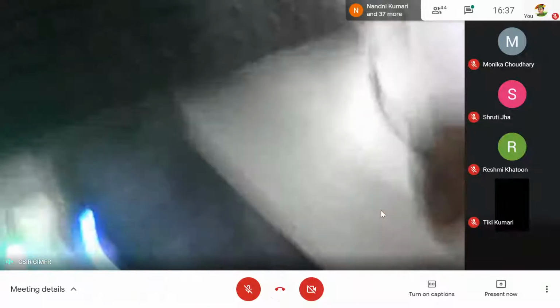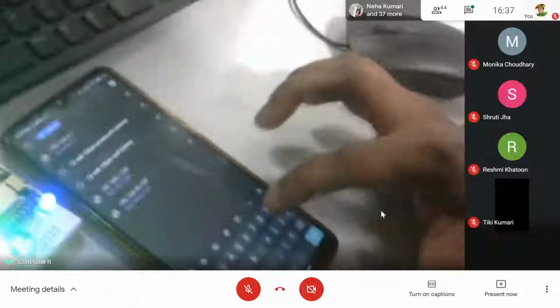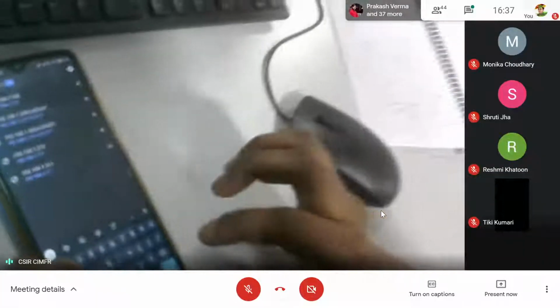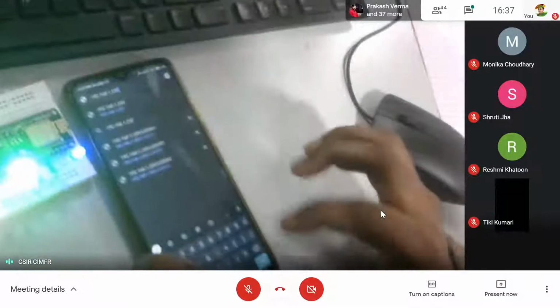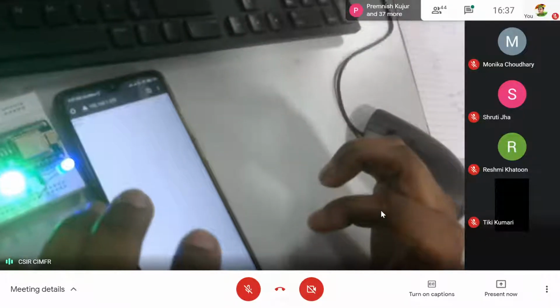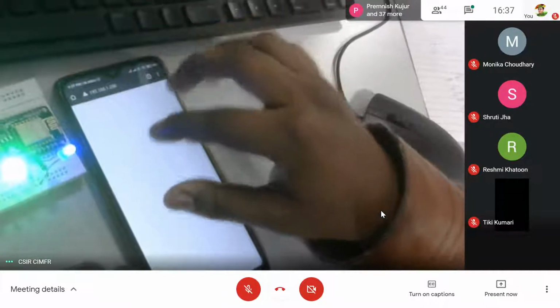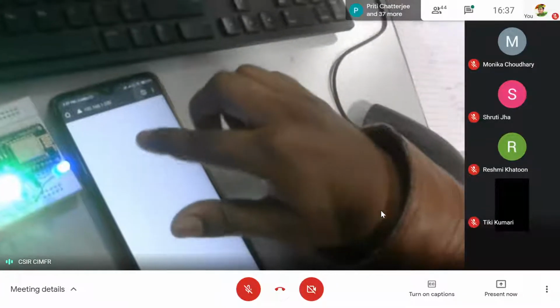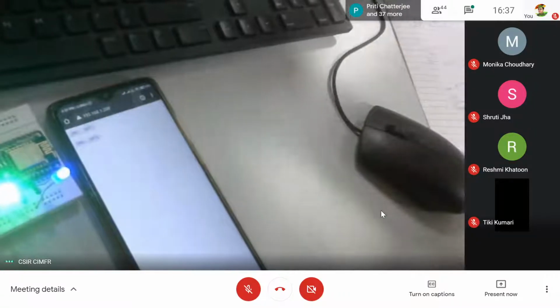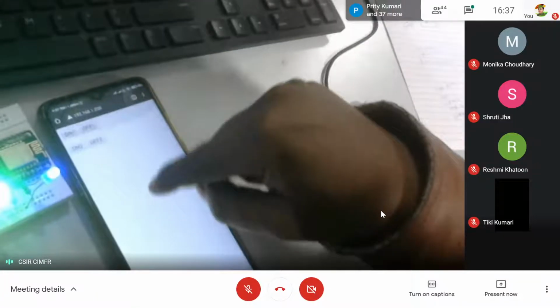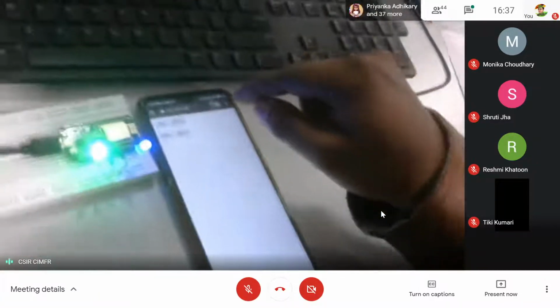You will have to give the IP address that our serial monitor was showing. That was 192.168.1.230. So after putting that IP address in the HTTP link, we will see two device options are given in this page.